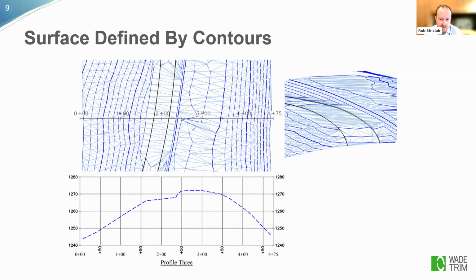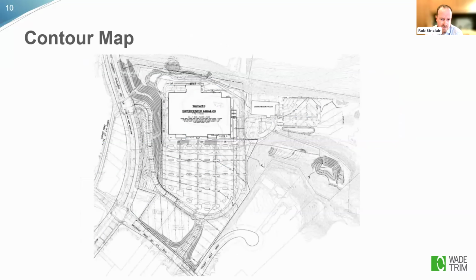It's very, very inaccurate. A lot of the engineering folks that I deal with throughout my career still want to use contours to build surfaces because they don't like the way that the Civil 3D contours are created or displayed. They complain about jaggedy contours or squiggly contours. My tip here is, if you have contours that don't look the way you want them to, more than likely the underlying data that you're using to create that is not correct. So go back to the drawing board and look at your corridor definition, your feature lines, your grading objects. It could be the settings in those. Keep that in mind as we move forward.